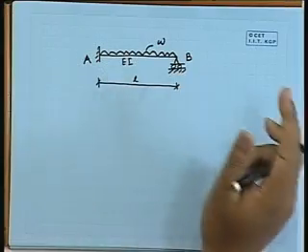Or if we just remove that support, it is a cantilever beam with a load, and that problem we have already solved because it was a determinate problem. There were 3 reactions at one point, that is support A. Now, due to putting a support here at the right end B, the problem became statically indeterminate, and it cannot be solved with the equations of statics.